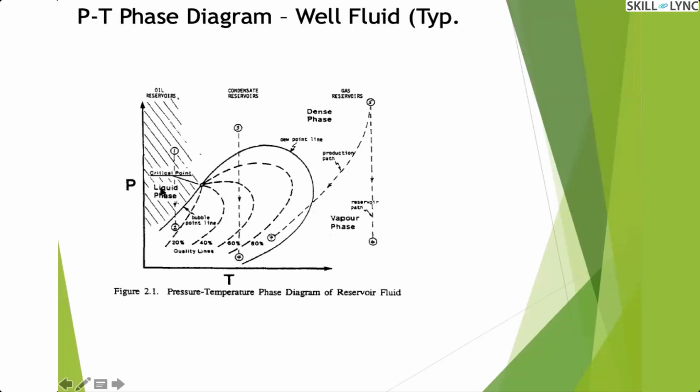So this is the liquid zone, which is at the saturated conditions. When you increase your temperature, it comes into this zone. When it enters into this zone, it will start vaporizing, so it will start existing in the two phase. The points across this line will be at the saturated conditions.